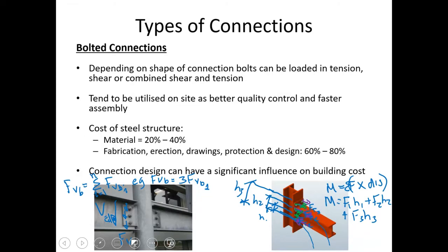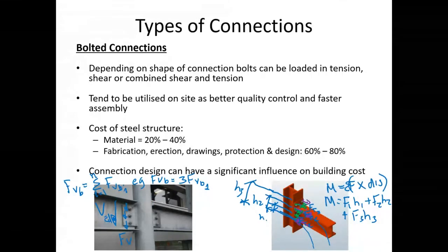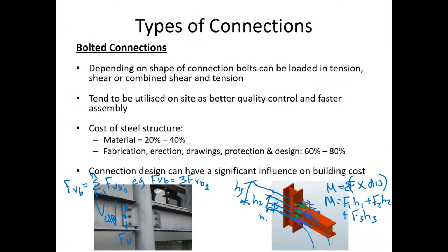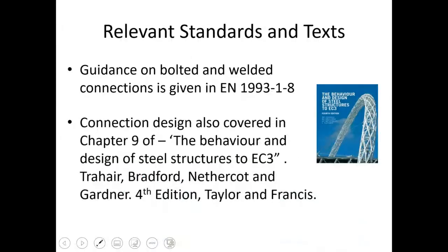So for example, normally when I'm pricing up a building, I'll work out what the mass is of all the primary elements, the beams, the columns, and so on. And then if I have simple connections, like in this case, I will then multiply the total weight by about 10% and then multiply that by the rate for steel, like about €2 to €2.50 per kilogram of steel. Whereas if I have a bolted connection, instead of taking into account the weight of connections by increasing the overall weight of the building by 10% based on the primary members, I'll increase the weight by 20% in there.